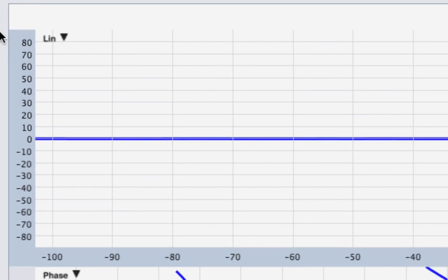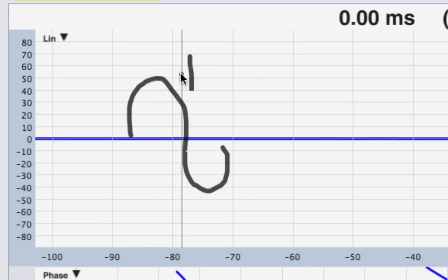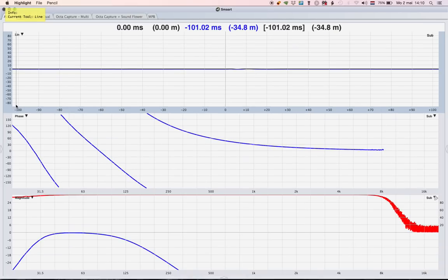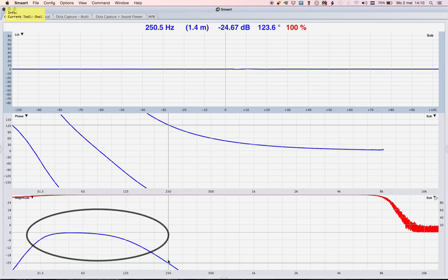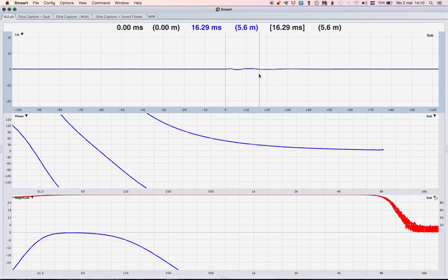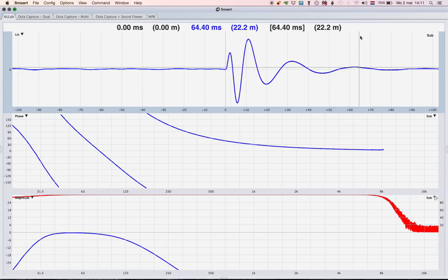And this scale is exactly the same as the one that we have on our oscilloscope. It will show you alternating current with positive polarity and negative polarity with values from 0 all the way to positive 100 and 0 all the way to negative 100. Because whenever you're dealing with band-limited signals, you lose amplitude for reasons that I will not disclose in this particular video. But in the article called A Track Named Impulse Response, you will find more information explaining why there is no amplitude. So I need to zoom in all the way to less than 1% to see the impulse response.